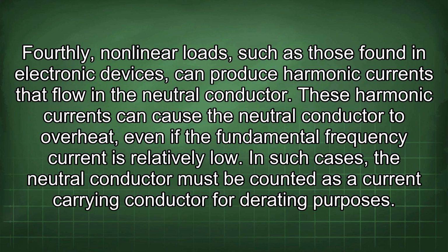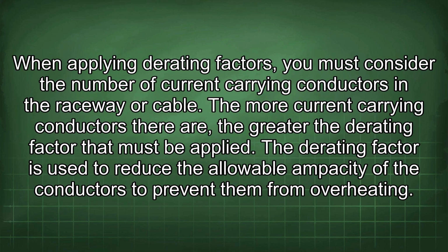Fourthly, nonlinear loads, such as those found in electronic devices, can produce harmonic currents that flow in the neutral conductor. These harmonic currents can cause the neutral conductor to overheat, even if the fundamental frequency current is relatively low. In such cases, the neutral conductor must be counted as a current-carrying conductor for derating purposes. When applying derating factors, you must consider the number of current-carrying conductors in the raceway or cable. The more current-carrying conductors there are, the greater the derating factor that must be applied. The derating factor is used to reduce the allowable ampacity of the conductors to prevent them from overheating.